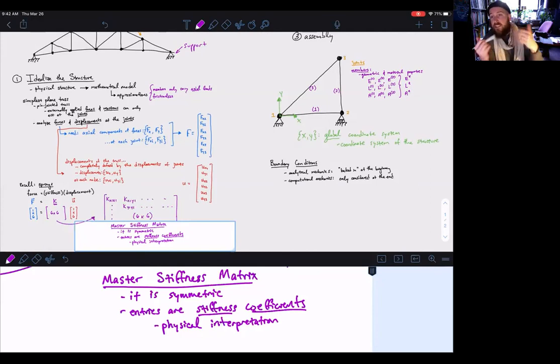As our physics gets more complicated, so if we, for instance, are going to allow bending in addition to stretching, then our stiffness matrix would include all the axial rigidity, so E, A, and L, but it's also going to include the bending rigidity terms.